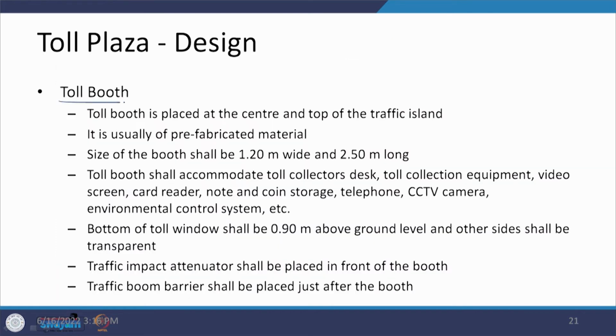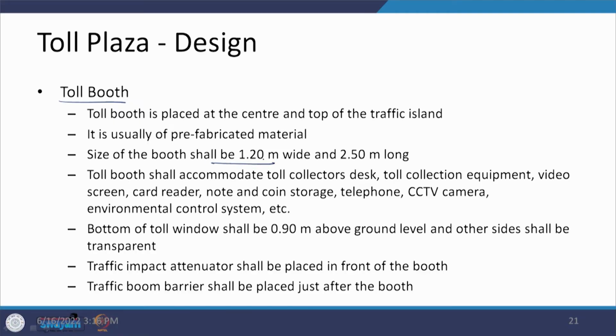Now, let us talk about another element, which is the toll booth. In the case of a toll booth, they are going to be at the top of the island, which is used as a divisional island, and the width of the island was 1.8 meters. The size of the booth is 1.2 meters wide and 2.5 meters long, and they are constructed by use of prefabricated materials, and there are different items which need to be made available within the toll booth.